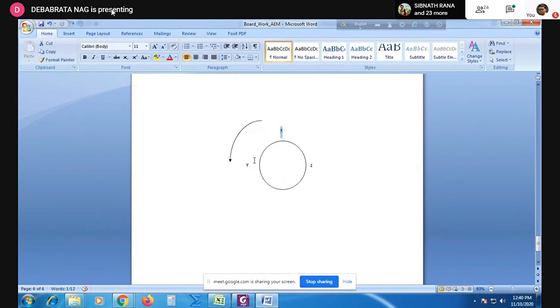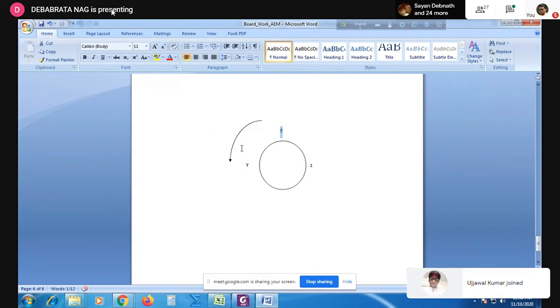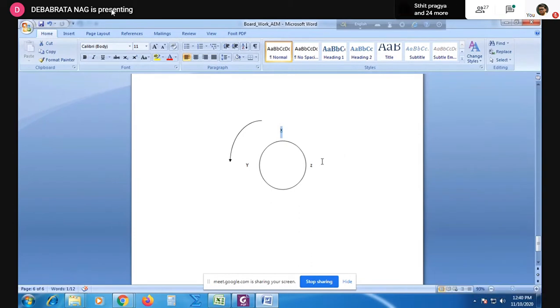So the summation My, the left hand side, becomes equal to what? Now it becomes minus Ixy into omega dot x, then plus Ixz into omega x square. And the third equation becomes the right hand side equation, all will be minus. In that case, the angular acceleration omega dot and the square of the angular velocity, these two will interchange their positions.